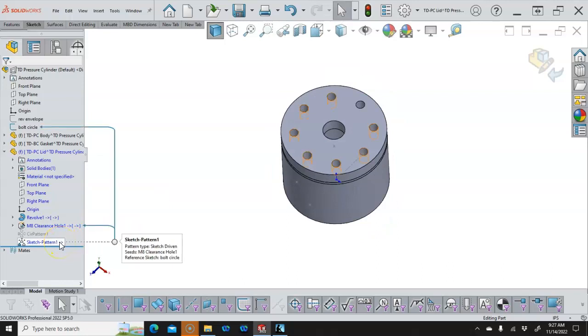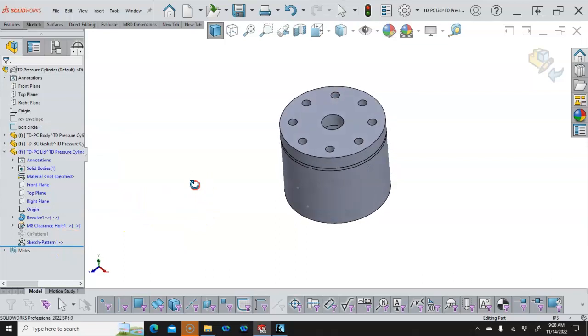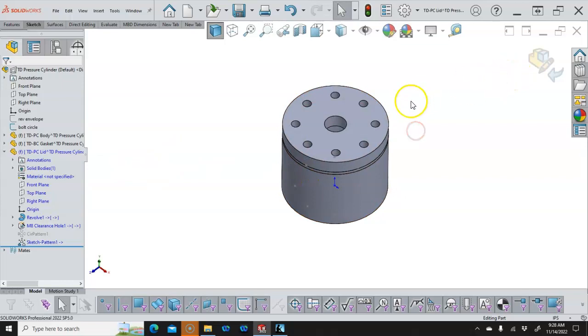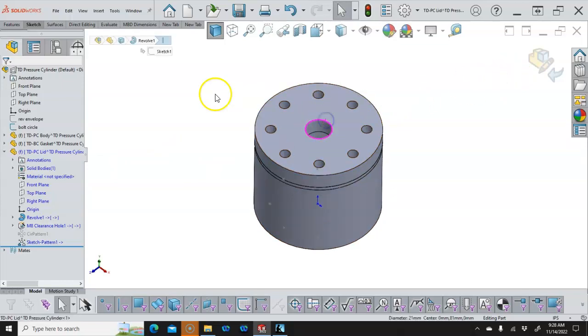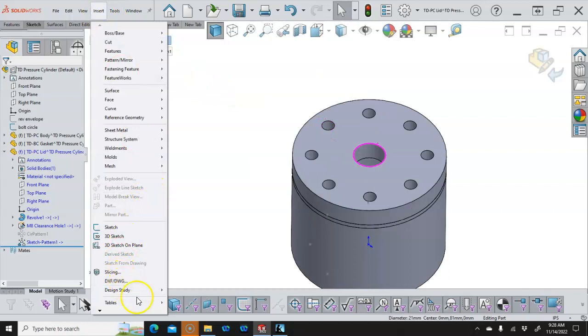The advantage here of the sketch pattern, though, is if I had a large pattern, and both of these over a sketch pattern, I'm sorry, the in-sketch circular pattern versus the feature patterns, that if there were a lot of holes, so when I do tooling plates with hundreds of holes, I pretty much want it to duplicate those features, not have to calculate it out of the sketch every time. All right, and then the last is going to be to insert the annotation